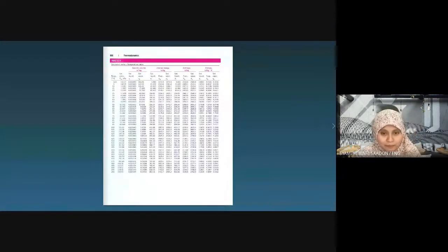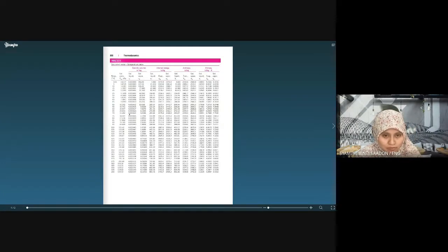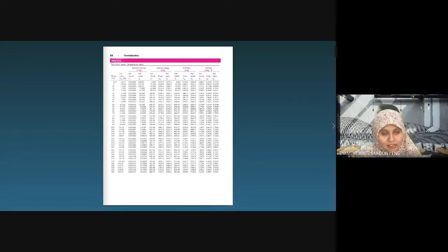And the volume of the tank. In order to calculate the volume of the tank, we can use the value of the specific volume here. The specific volume is meter cube per kilogram, and then we have to multiply with the 50 kilogram given. So back to this row: 90 degrees, 70.183 saturated pressure, and then the liquid, because it is stated saturated liquid water.